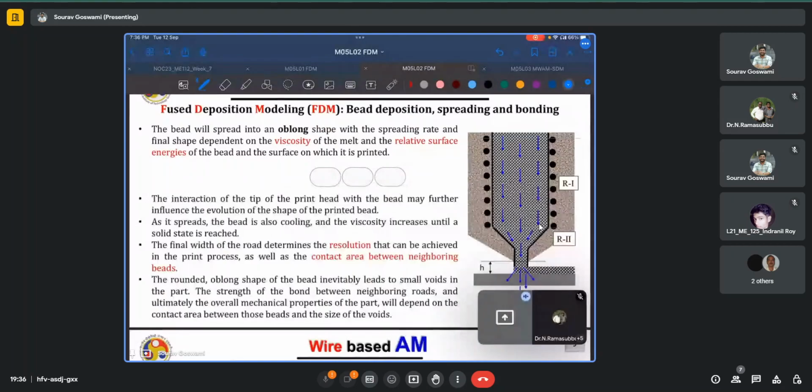Again, as we saw, usually for the general case, the deposited bead would have an oblong or elliptical cross section. So our deposition is again into the plane. And if we take a cross section, we see these oblong shapes. Based on the hat spacing, so maybe the distance between the center of two neighboring tracks, based on the surface tension phenomena of these two surfaces, based on their molten state or their rate of solidification, different sorts of inter-track porosities or even inter-track phenomena might be observed.